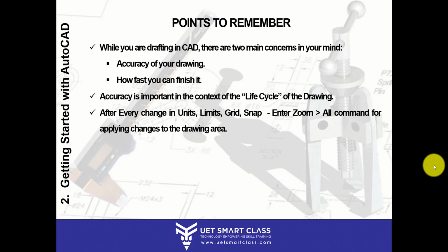You need to understand the difference: if I say draw a rectangle, I can draw it through a line, through a polyline, through a polygon, or through a rectangle command. From all these four, definitely a rectangle can be the resulting object, but you need to understand which one will give you accuracy. Definitely, you can select the one which is faster for you.